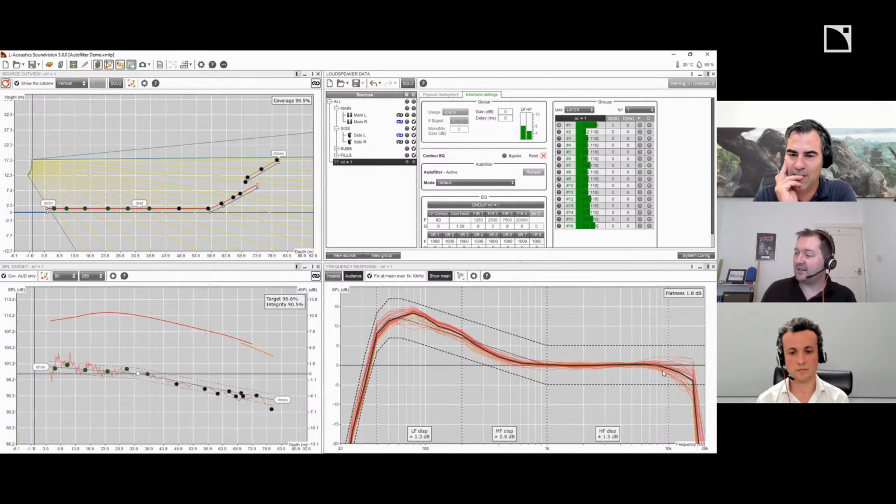So we can see the high end's a little bit better, so it attenuates a little bit more in the near field because of the discretization. But is that worth twice as many amplifiers? I suppose that's a really interesting choice now for the user, for the sound designer: is it worth that added value? Because honestly, I don't see a huge difference other than maybe the first 2 or 3 enclosures, the bottom 2 or 3 of the array, which seems to be the only place.